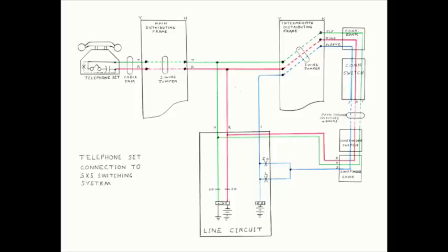So let's see how these cross connections are utilized to connect a telephone set to the step-by-step equipment. Let's assume we are establishing initial telephone service for a new customer. The customer is being provided with single-party flat-rate resident service. The telco installer will get a service order that will assign the telephone to a particular cable number and cable pair number. When installed, the set's tip and ring wires will be physically connected to a particular cable and pair termination on the vertical side of the main distributing frame.